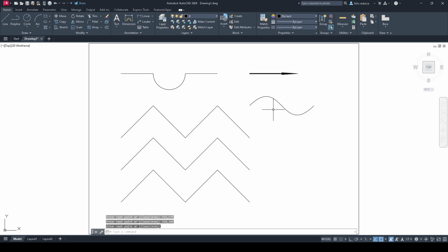And it created a special line for me here, a curve, which when I click on it, you can see I have some control points on the outside. And this is based on the way I draw the line. This is with the control points, with the line through the control points, and I have another mode of drawing this with the line fitted on the control points. So let's try the second kind of spline and see how that works.